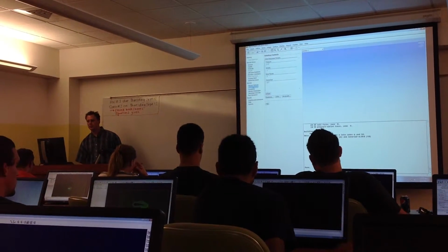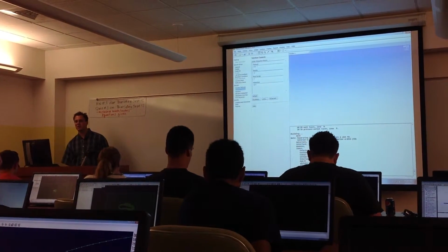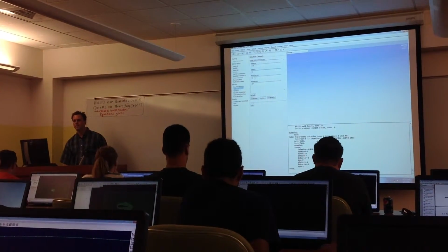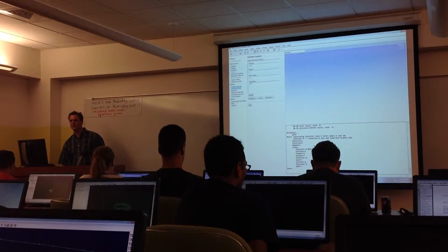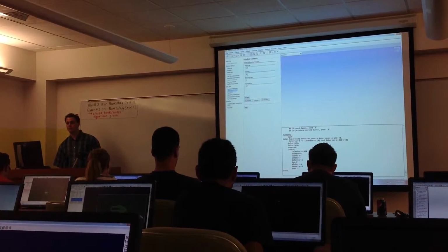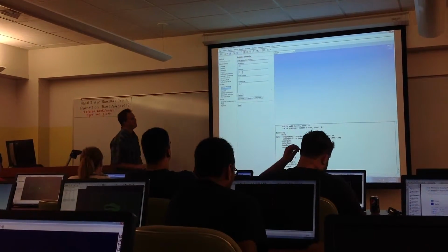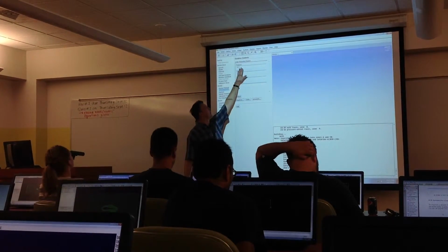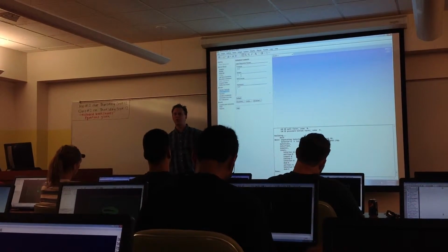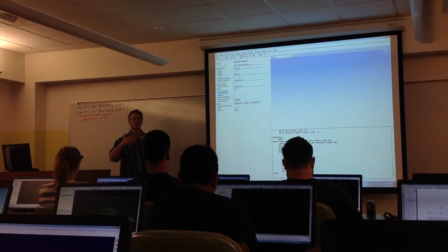And solution controls. If you run into trouble when you run these things, these are the numbers you're going to want to change. You can lower this to 0.7, maybe this to 0.3, for pressure and momentum. These are relaxation factors, and the lower you make these numbers, the less the solution will be allowed to change each cycle.